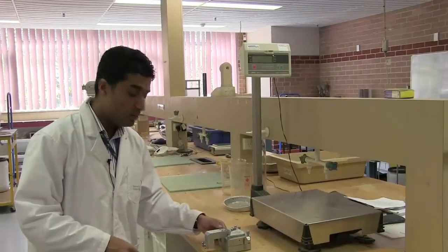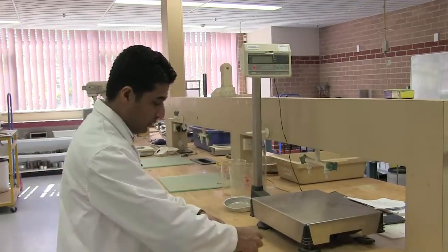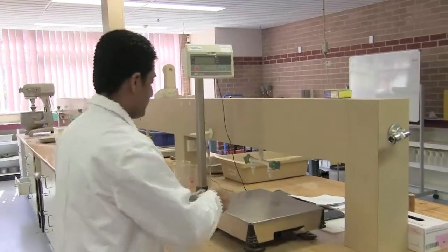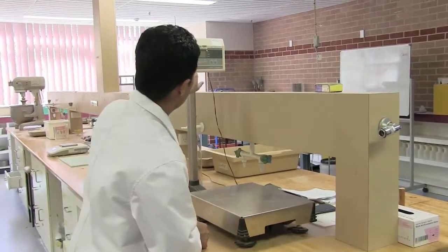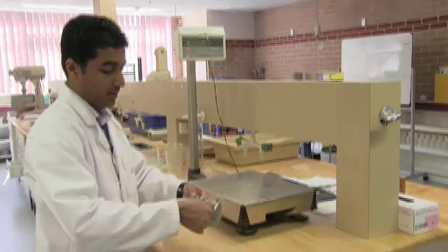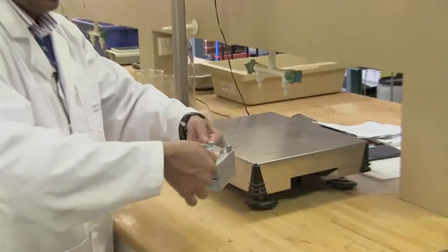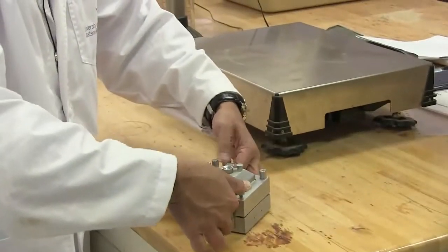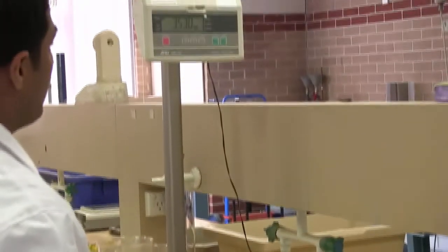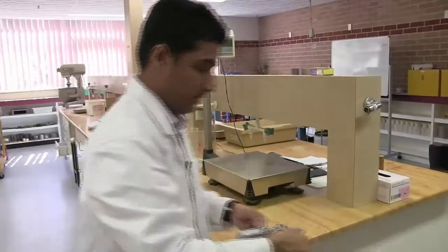So once the loose sand sample is prepared, you measure the weight of the soil sample using the scale. You hold the sand sample in the shear box like that. Use the hooks as well as the guiding screws to handle the sample. That's 3.530 kilograms. Record the value for your calculations.